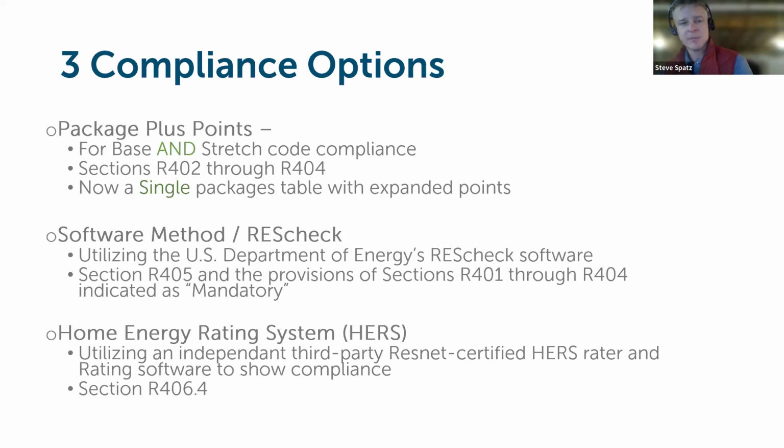And then the third option is to work with a third party, a HERS rater, who will do more detailed energy modeling of the building and verification as well, which involves coming out, and since there is no code enforcement, no code inspection for residential construction here in the state of Vermont, the HERS rating option gives you the benefit of having a third party come out and verify that you're technically compliant to the code and do some performance testing to align with that outcome as well. So these are the three options available in the code to show that you've complied technically.